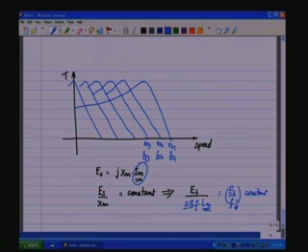And if we have to increase the speed beyond the base frequency, then the voltage cannot increase any further. The voltage has reached its rated value. But I can increase the frequency to go beyond this, but if you increase the frequency, the flux decreases. So therefore, beyond a particular point, you will have only field weakening. So I could have a constant flux, constant torque at this point.